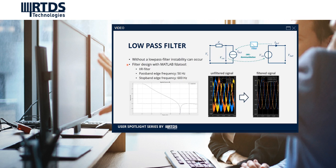I used Matlab because it is more convenient to design a filter than in RSCAD. I used an IIR filter to achieve minimum filter order with a passband edge frequency of 50 Hz and a stopband edge frequency of 600 Hz.